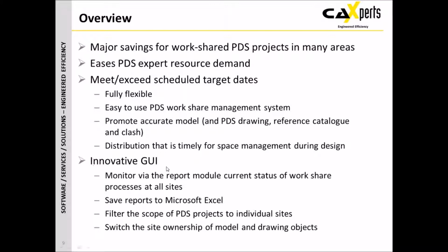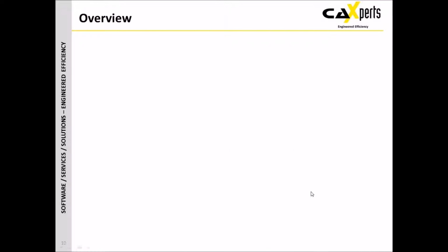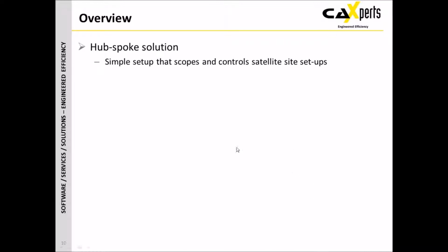From a graphic user interface point of view, it enables you to monitor via the report module the current status of workshare processes at all sites. It saves reports to Microsoft Excel, and it filters the scope of PDS projects to individual sites. You can also switch the site ownership of the model and drawing objects, and again I'll explain a little bit more about what we mean with that. It is a hub and spoke solution, so it gives you a very simple setup that scopes and controls the satellite setups themselves.